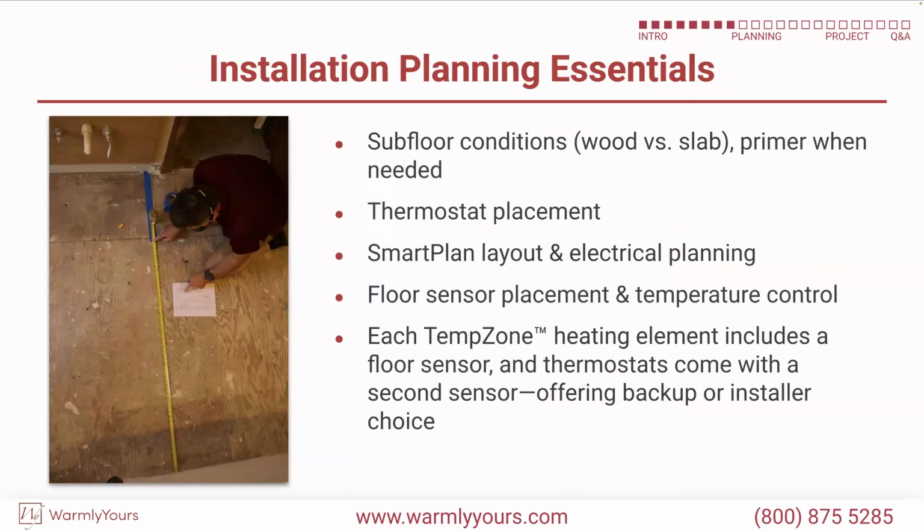All right. So what are some installation planning essentials that a sales rep needs to know from their point of view to be able to quote you the correct thing? And how are you going to interact with them with these different things? One of the first questions I like to ask is, what is your subfloor? Are you starting from the first floor of your home on a wood subfloor, or second floor of your home? Or is this going to be on a concrete slab, like in your basement or your mudroom, or you're turning an enclosed porch or something where it's an existing concrete slab and we're going to go over it? One thing we want to know about that is if you are going to need a primer when you're going over the subfloor. That's going to be important.